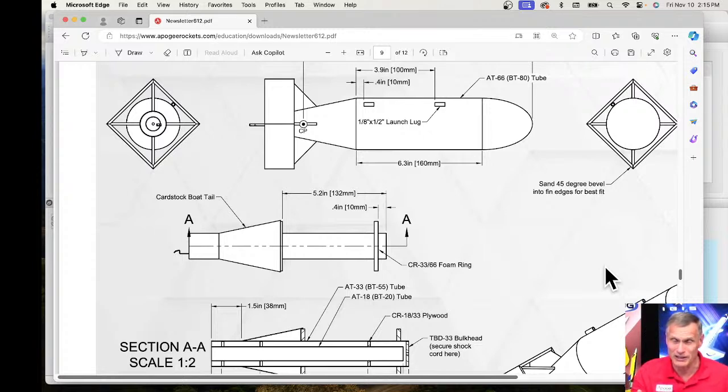Getting the parachute inside can be tricky because, depending on your design, you may not have a lot of room inside the rocket. So getting the parachute in there, around the tube, is going to be a challenge. Streamers work really well, but if you're using a streamer, you're limited to a pretty lightweight rocket. The other disadvantage is that when the motor comes out, they're known to be a little bit more powerful and more stressful on that shock cord. I've built a lot of rear ejection rockets, and they're more prone to separating in two parts than a regular rocket. And you know how easy it is for a regular rocket to separate. So just imagine a rear ejection, it's going to be more prone to separate.